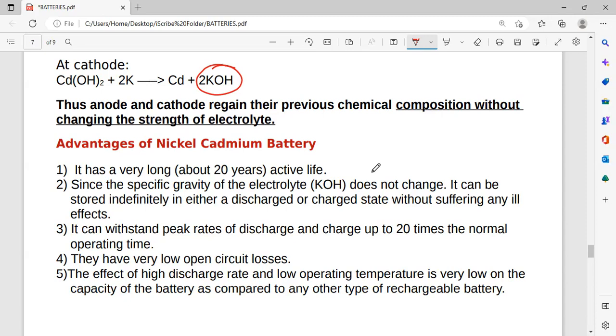GMDSS, general use, lifeboat batteries, emergency generator batteries, all have to be changed within 2 to 3 years of being installed. Whether they are in good condition or not, it comes up in your plant maintenance system. These batteries are to be replaced, so you get it and replace it.